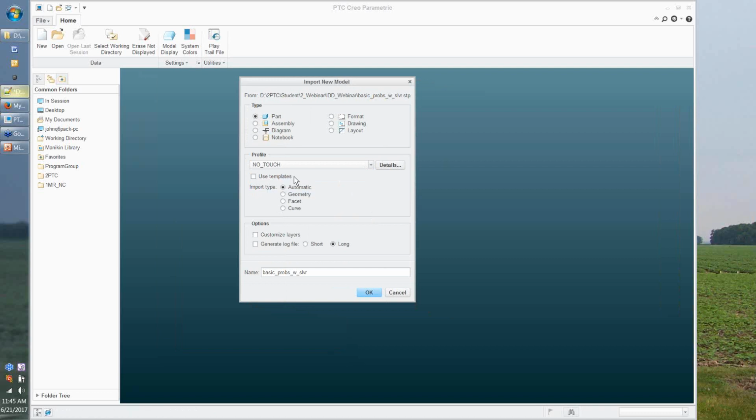The reason I don't use my own part template is because I want to check and spy on the accuracy of the model that the originating system used when the model was created. Because a part of repair reality is that you don't get back math you never had. And your own part template can in fact have better accuracy than what the originating system used.